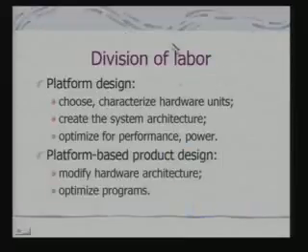So in a sense, there is a division of labor: the platform design and platform based product design. Platform design is to choose and characterize hardware units, create the system architecture, and optimize for performance and power. Platform based product design is to modify the hardware architecture and optimize your program so that you get the best performance.